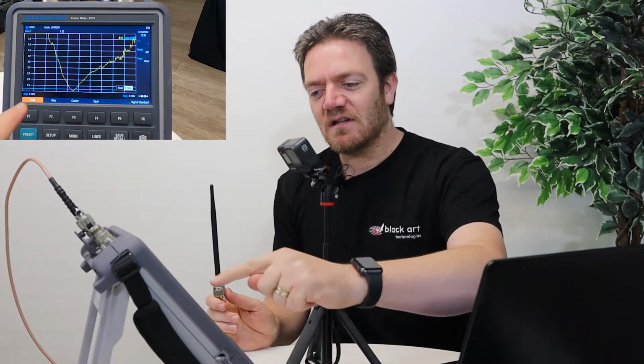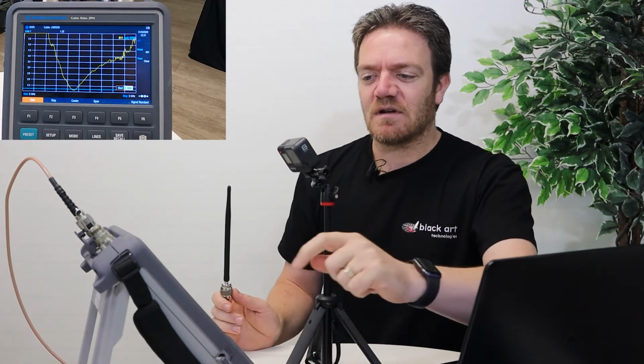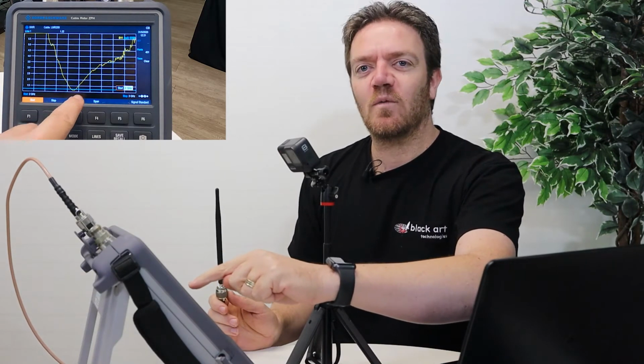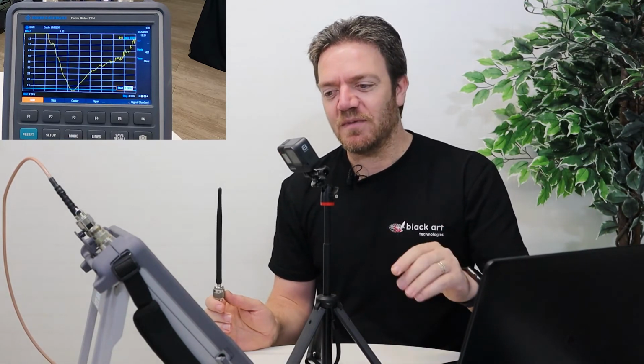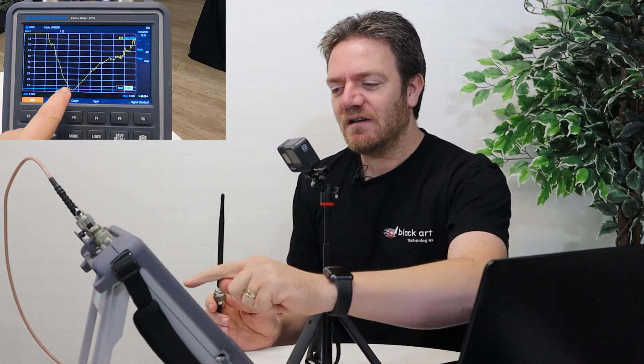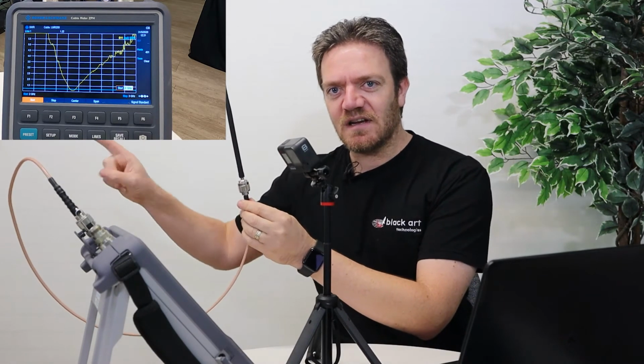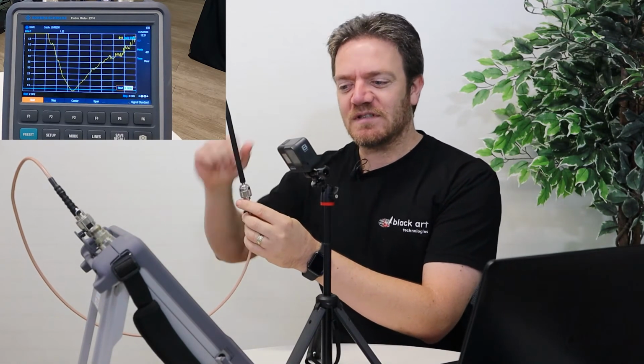So that's what VSWR tells you. It tells you where it works, and how good it works. I remember I set the value 1.5, so there's a line there. I just want to see my screen so I can see what's going on. There we go. The second line from the bottom is 1.5 to 1. I use that as a measure to say that's good enough, because that's the level it should be. 2 to 1 is often used. So basically, there's a 1.5 to 1 band where this antenna is at least transmitting the signal, and it would pick it up if there was something receiving as well.